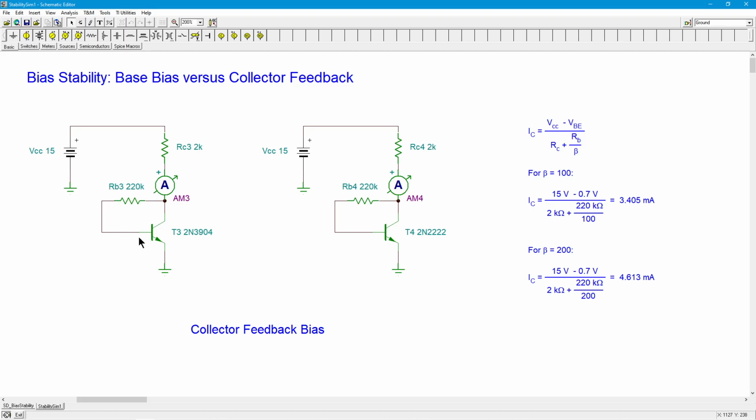So that decrease in the base current tends to at least partially offset, or fight, however you want to look at that, the tendency of collector current to go up. So theoretically, this thing should be more stable. This is an example of what we call negative feedback. It's trying to stabilize the circuit. It's trying to come up with a nice set point, right? So you get too much current, which increases the voltage on the resistor, which decreases this voltage, which in turn decreases this voltage, which decreases the base current.